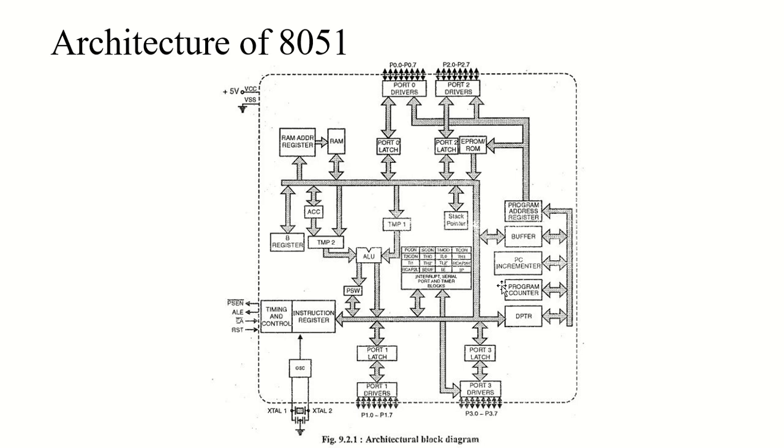It is used to hold the address of a byte in the memory, and it keeps track of the execution of my program, right? The program instruction bytes are fetched from the memory locations addressed by the program counter, and whenever the power supply is switched on, the program counter resets to 0.